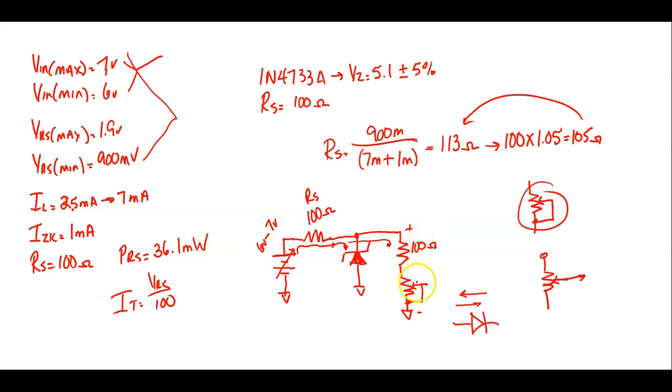Over here, this is my load. So I've got a series resistor right here. So that means all the current flow through this has to go to that resistor. So I can calculate I load by taking what? V across this resistor. We're going to have to give it a name. And so we'll call it VR1 divided by 100 ohms. And that will give me my load current, right? You understand? And it's 100 ohms, so it's 10 millivolts per volt. So a lot of times we can do this without what? Without math. I like 1K. 1K is 1 millivolt per volt. 100 would be 10 millivolts per volt.